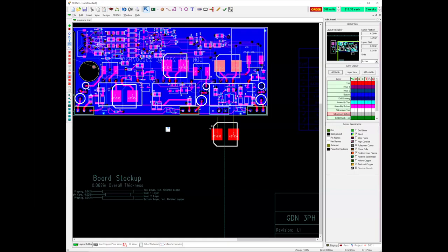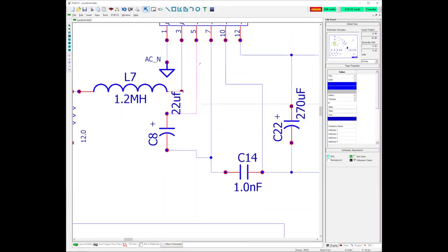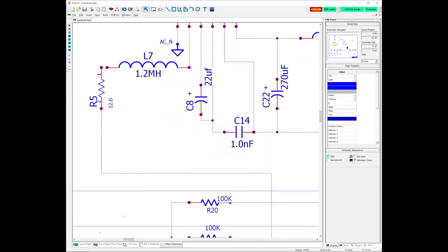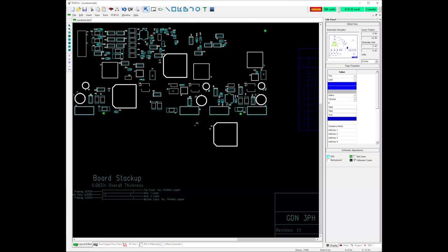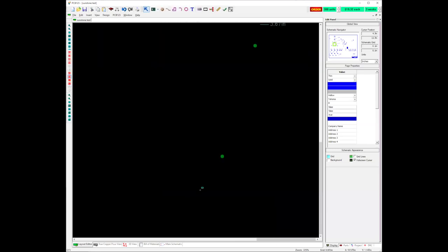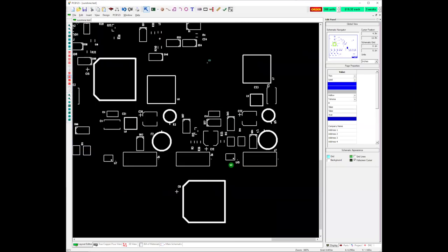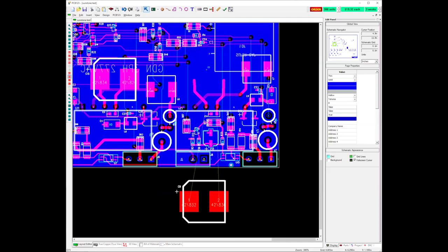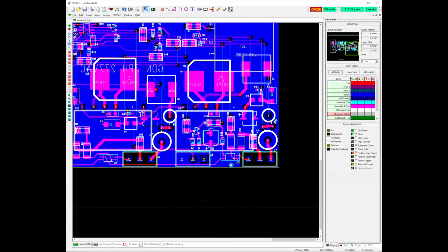Now I can go in and delete that guy. The wires stay. Put that right back where it came from. Go to my layout editor. And all that's left to do is take this part, plunk it down on those wires, and off we go. It's connected. I've got no errors, no guide wires, no disconnected anything.